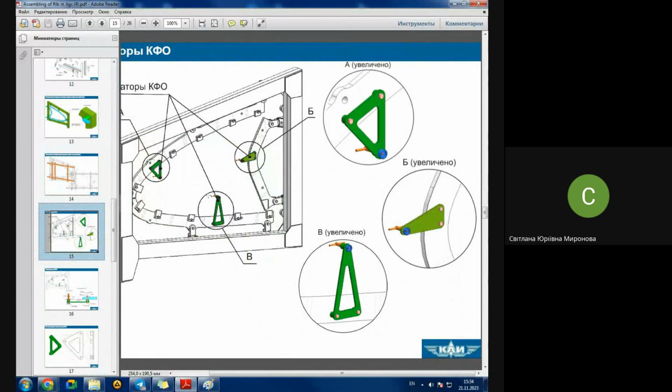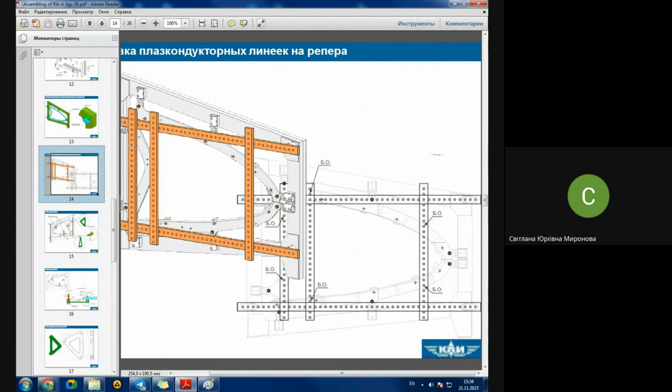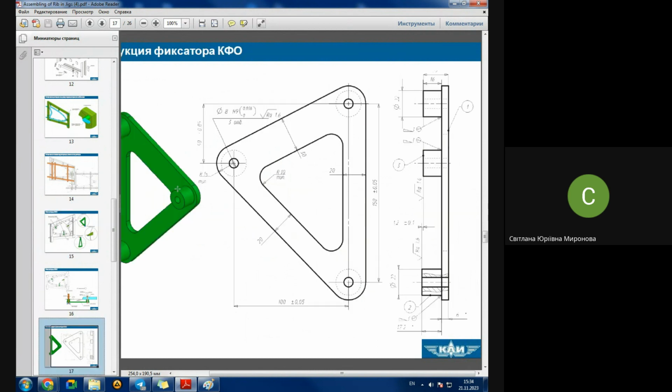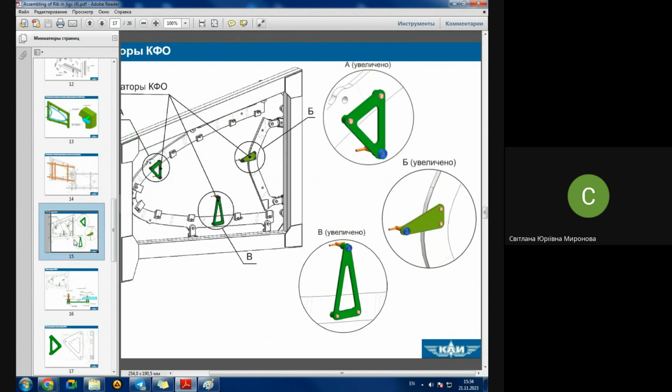Look at this CFH locator. It's not clear why they have a second ruler. What for? They have some rulers here, for instance. They have already located this locator. What is the second ruler here for? Because they need to place here additionally a CFH locator. That is why they have one ruler somewhere here, the next ruler in the line of the CFH locator, and so on. CFH locators, which look like brackets with bushings, are also located by those rulers.